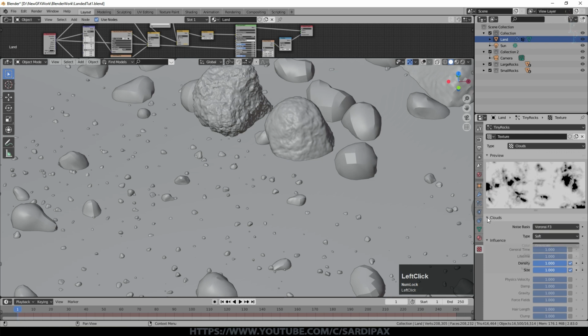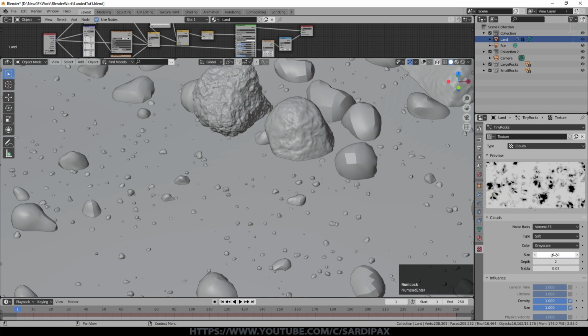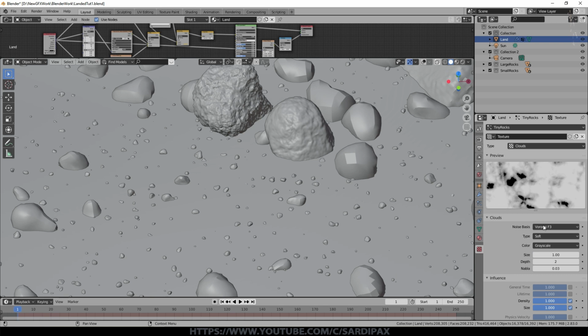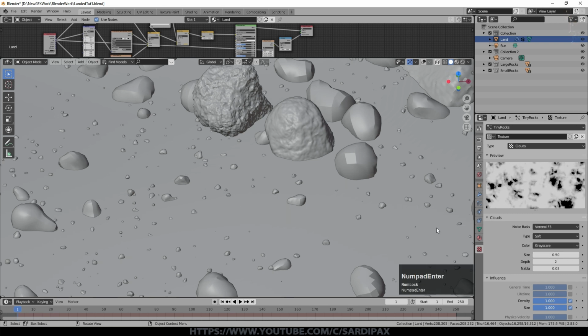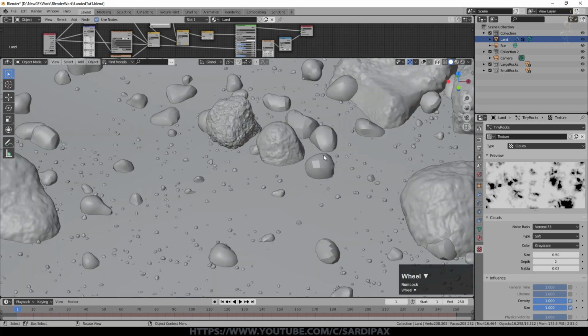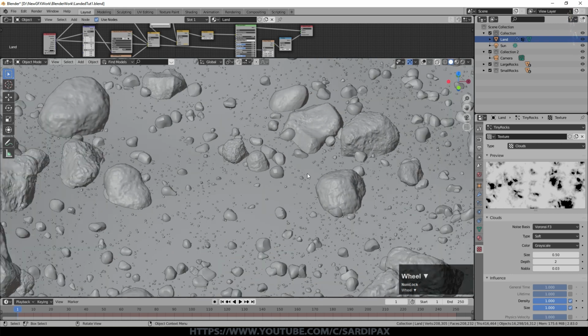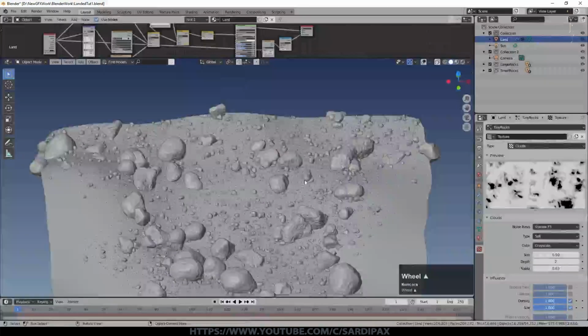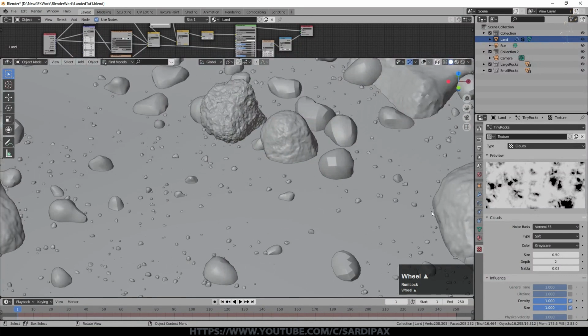And as I said, what we can do is play around with things like the size and the scale. So I could try 0.3, so that's a higher frequency one, or go up to even 1, and it just makes the individual areas bigger. I think something like 0.5 is fine. And it's not that we're looking to see a pattern, it's just that we're looking to see variation. Some areas where there is gravel and some areas where there isn't.